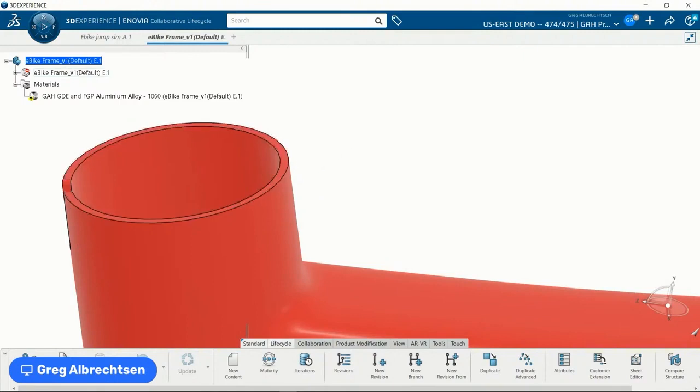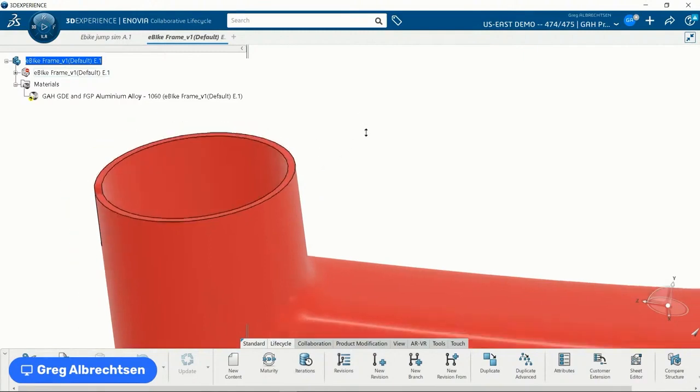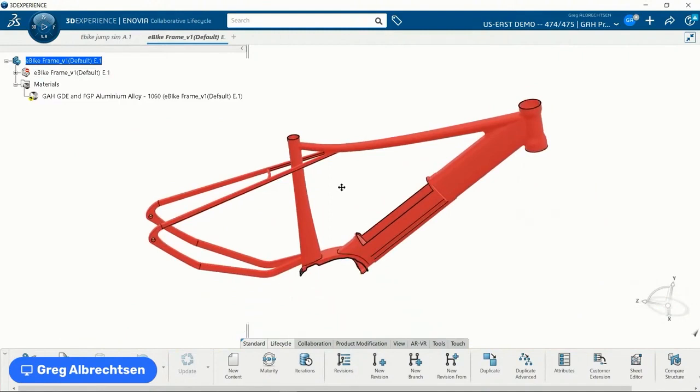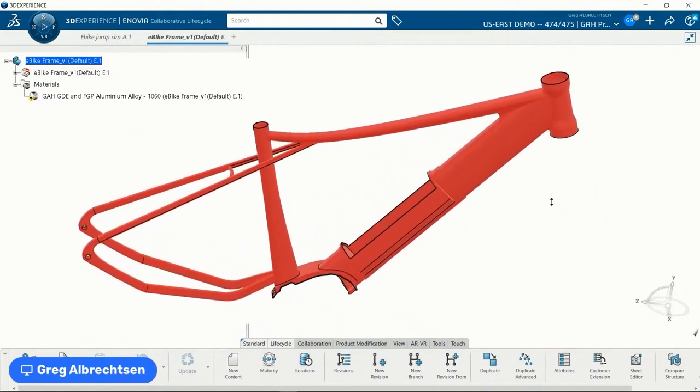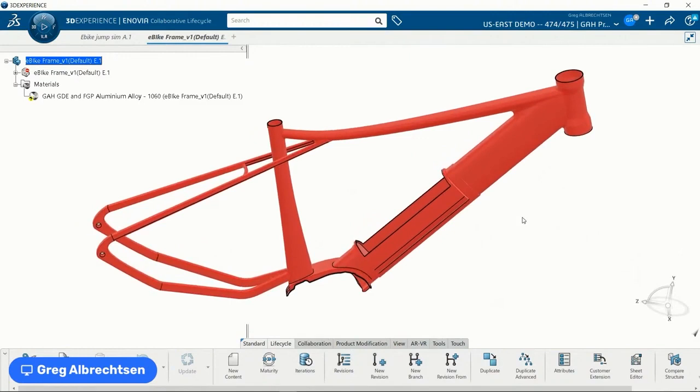And if I had 2 elements through the thickness on that tube, wow, that's going to make so many elements on this model. And it's just not going to give you the bending forces and bending moments that you really need to represent the displacements and the stresses. It'll probably be a little bit over stiff.